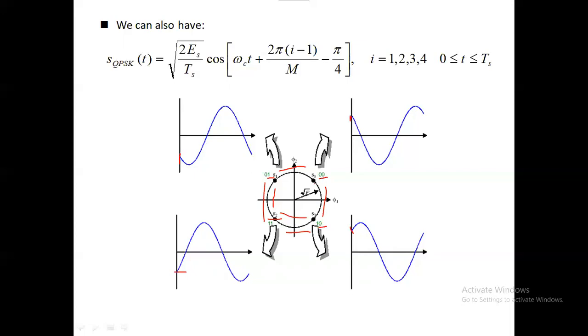reducing the probability of bit error as compared to the probability of symbol error, because one symbol in error means only 1 bit is detected erroneously. So instead of S0, if the decision boundary goes up to here and we detect S1 or S3, we have only 1 bit in error instead of 2 bits in error.